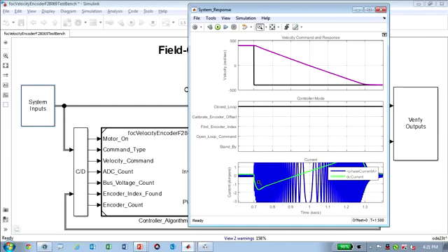Now, how I fix this is going to be dependent upon kind of who I am and how I want to approach the problem. Some of my colleagues are battery guys, right? And what they might do is they might say, okay, well, what I actually want to do is make a better model of the battery or a better model of the power supply. And I can say long term, that's a great thing to do. But the point of this model is for me to be able to test software. So I can just add a test into this that says, hey, if I push a half an amp of current back in, just shut things down.